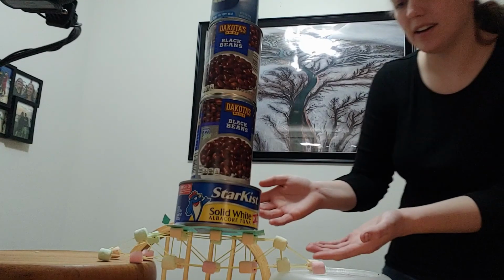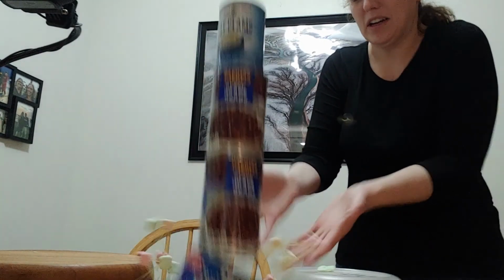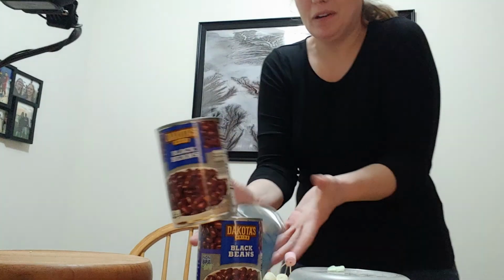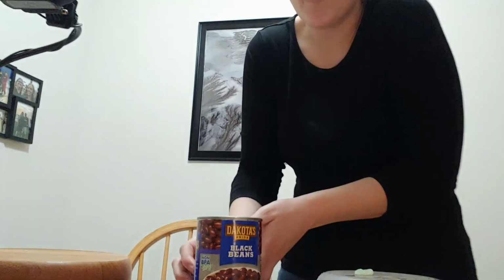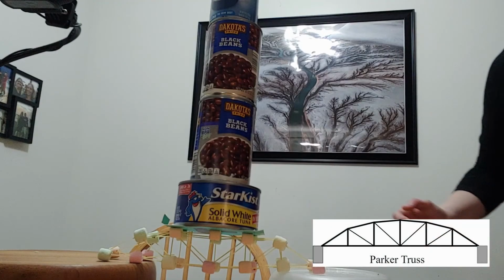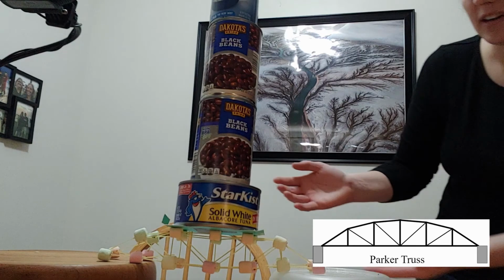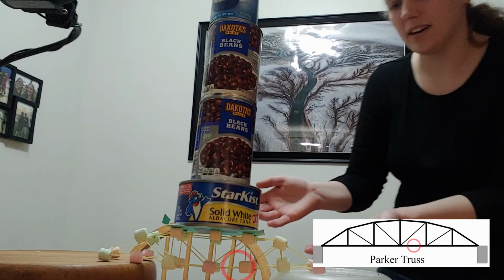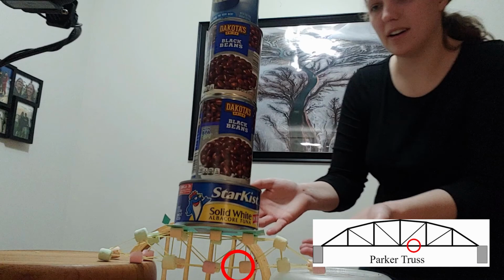And one more time. Okay, so the Parker bridge, in comparison to the brown bridge, was really, really stiff. Remember, the brown bridge failed on its weak joints, but the Parker style truss failed because the pasta actually broke first. But we can do one better than this. In the Parker video, we could actually see where the first piece of pasta snapped. Yeah, right there. So if we know how to analyze our truss, we can check whether that specific piece of pasta was supposed to be in tension or compression, and then we can even see how much of the total load it should have been carrying.